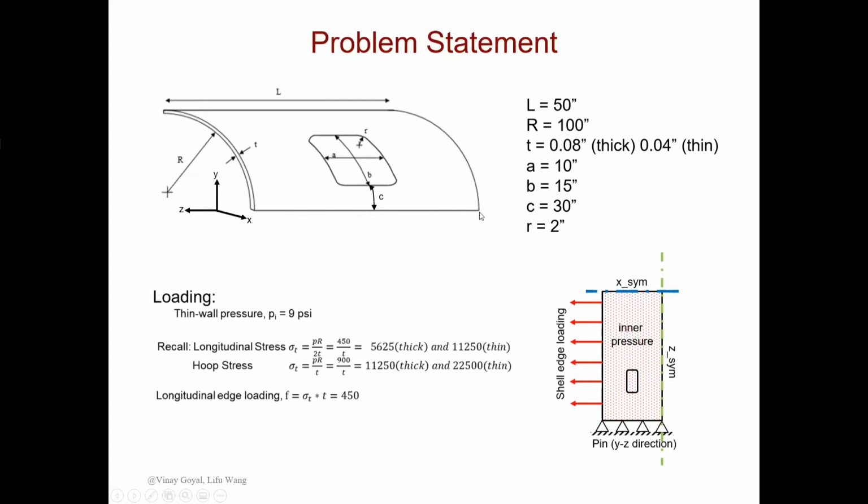For the bottom surface, in the real case it cannot move to the right or to the bottom, so we apply a YZ direction pin to this edge, but we allow this one to expand, meaning it has x direction displacement.